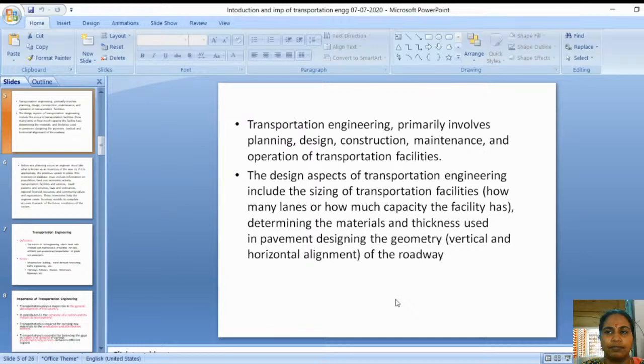Or if you are going for a preliminary survey, we can take a chain or leveling staffs like that. Linear measurements; a linear survey can be done. So we can take minor instruments also for a preliminary survey. So we have to plan first of all how many ways are there to go there, and after planning only we can design which type of road is best suitable.